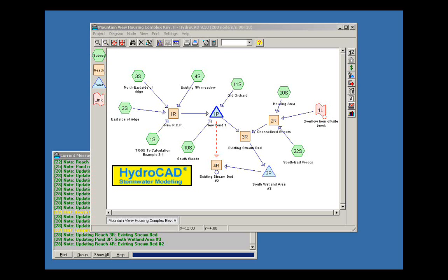Yeah, and we had another question here. A couple of questions, actually. Is there a size of project where use of Carlson HydroCAD makes sense, or does the system make more sense for 1 or 2 acre sites? I think it's entirely a matter of the time it will save you extracting the data. What we see is that getting the subcatchment areas broken down is more than 90% of the data that has to be entered into a given HydroCAD model. And certainly if you've already got these layers set up in AutoCAD, whatever platform you may be using, there's going to be a big savings to you in extracting that information.